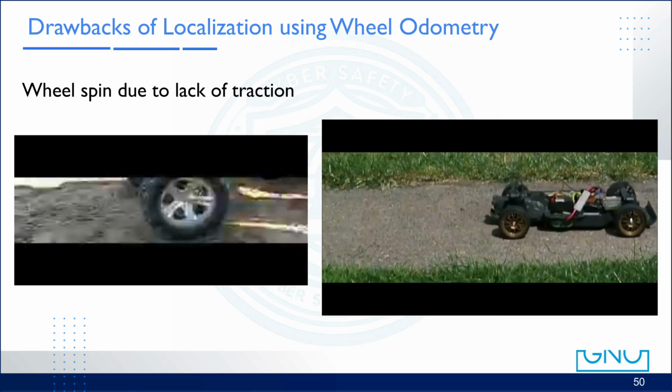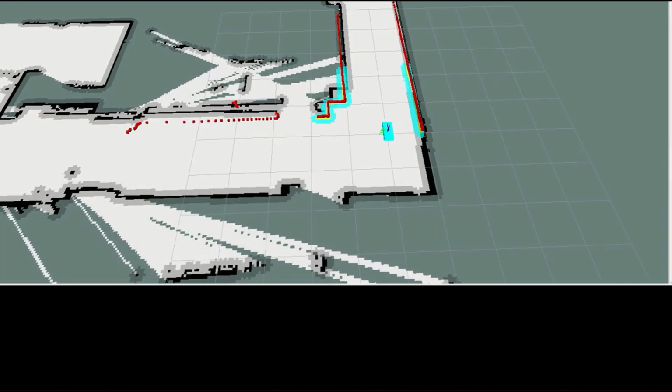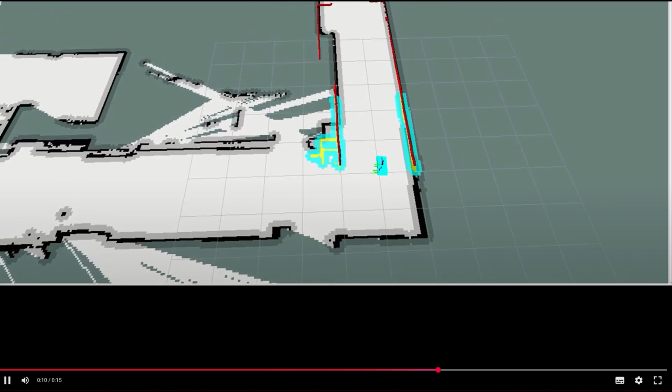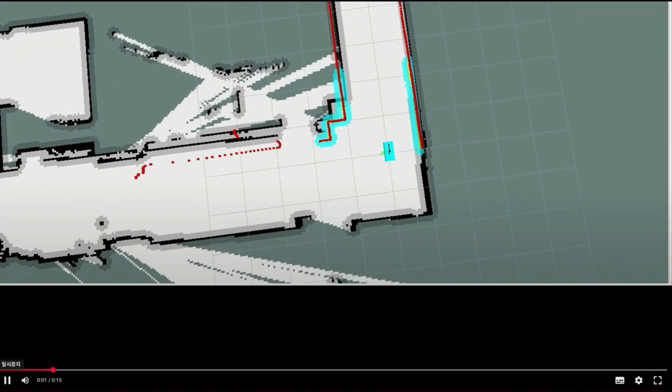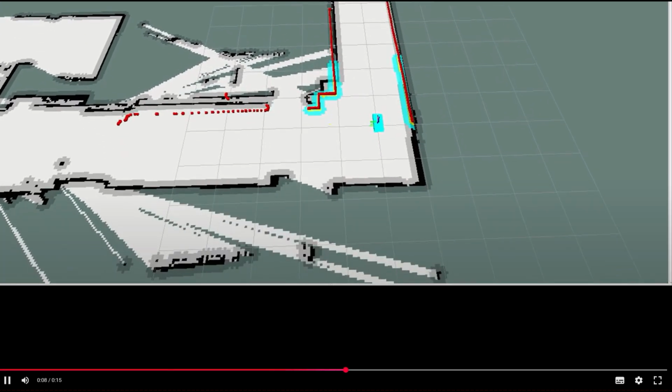completely wrong pose estimate. Similarly, odometry obtained from Hector SLAM also has limitations. Since Hector relies entirely on scan matching, it works well only when the environment provides distinct geometric features. However, in long, smooth corridors with parallel walls and very few features, the scans look almost identical from one time step to the next. As a result, the scan matching algorithm cannot detect the small changes in movement.